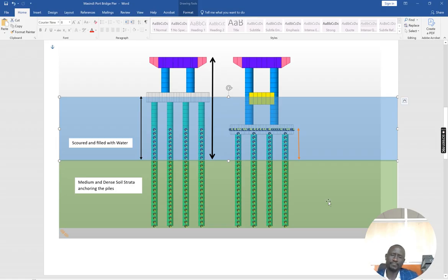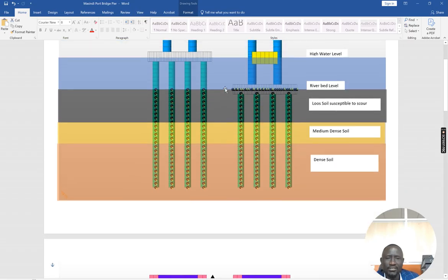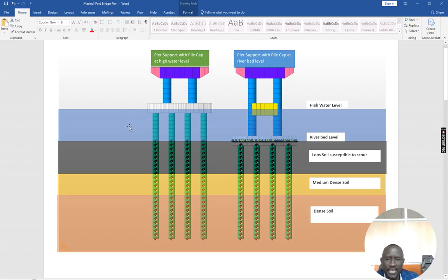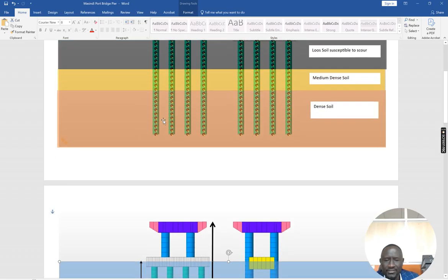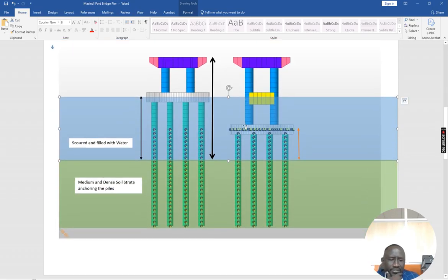That is the water depth. So water depth now goes like twice, depending on the scour depth. The scour depth has to be calculated. You guys, I know you have the formula. I'm not going to dwell on that now, but I wanted to see the implication. So at the beginning you have maybe, say, X or H1. After 20 years or 25 or 30, depending on the soil particle and the treatment around here, the scour can go twice or thrice or 1.5 times the